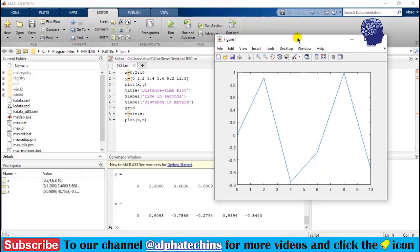So you can see that we have plotted some sort of sine function, but the thing to be concerned about is that we have skipped our first plot. We have not skipped, but MATLAB skips the first plot. So what should be done is that we have to use the figure function.